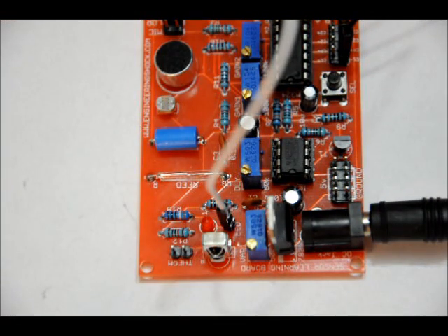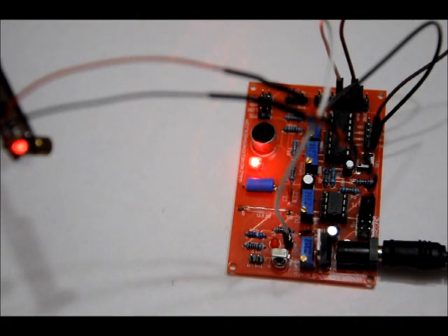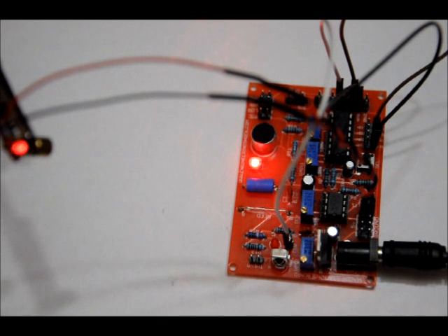So why don't we plug in our laser attachment and point it at the LDR, and then we can make a laser tripwire. So I've connected the laser to the power supply pin block, red to 5 volts, black to ground, and I'm pointing the laser at the light-dependent resistor. Now our circuit isn't very sensitive right now, but I'm going to go turn off the lights, and I'm going to come right back and I'm going to break that laser beam.